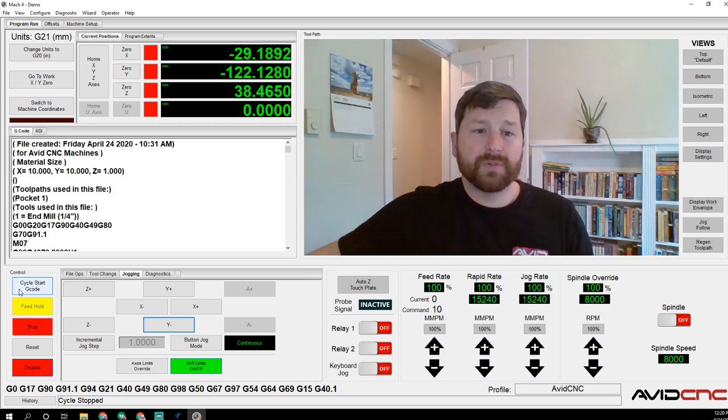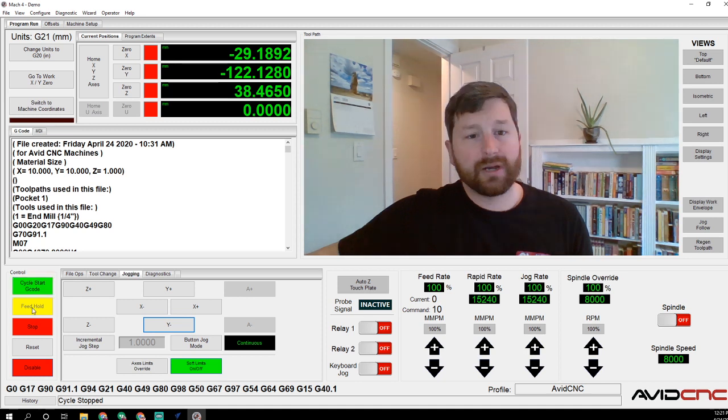So generally speaking, the emergency stop button is for exactly that. It's for an emergency. If I'm noticing that I'm getting close to a screw, or that my work holding is becoming less strong than I would like, I am not hitting the emergency stop button. I'm hitting the feed hold button, right? In the event you do hit the emergency stop button, some people say, well, how do I get back to where I was in the program?